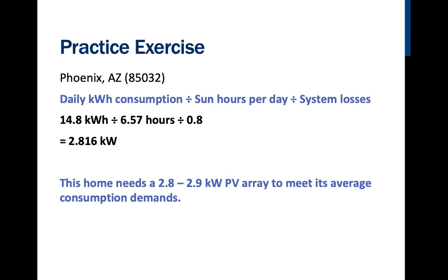That is absolutely bizarre. And we scoped out one for a Midwest system, and that was essentially double that size. So let me run this number real quick. 6.57 divided by 0.8 equals, yep, son of a gun. That's crazy. Well, long story short, they need half the amount of modules to do the same amount of work in Arizona as in the Midwest.